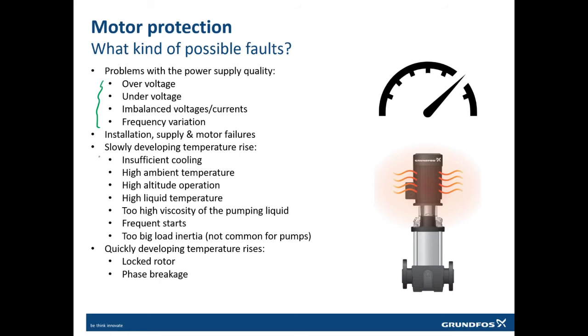Like your motor is developing high temperature but very slowly. For example, your ambient temperature is high, but it will not burn your motor instantaneously. It will burn your motor after some time. Or high altitude, you don't have enough air to cool down the motor. Or high liquid temperature. For example, the liquid is 150 degrees centigrade, and the pump is designed for only 110 degrees centigrade. What will happen? This additional higher temperature will go through the shaft to the motor, which will again overheat the